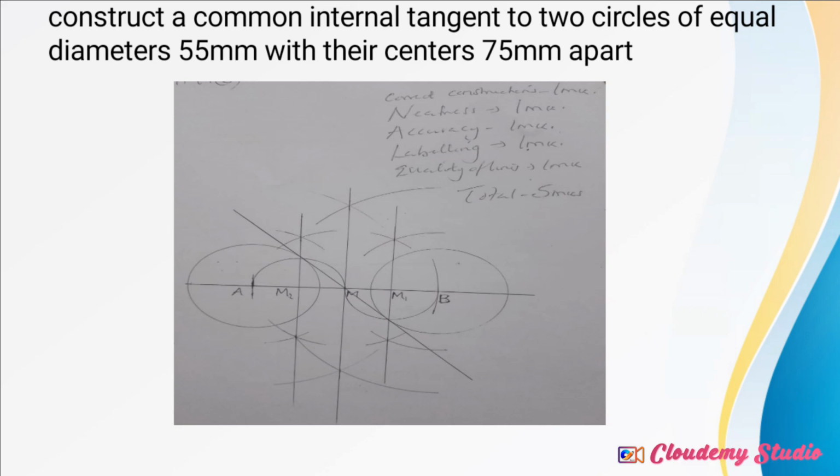Then after doing that, you will construct a midpoint by dropping a perpendicular bisector that cuts through AB. The same procedure applies for construction of midpoints: start at point A, stretch your compass above 3/4 of that line, making an arc above and below. Starting at point B, stretch your compass again using the same radius as in the first step. Make an arc above and below, and join. So it will form the first midpoint.